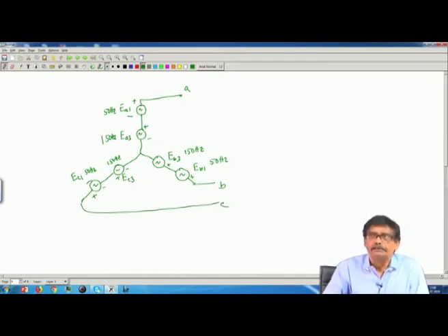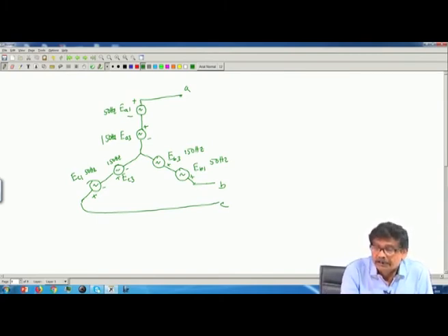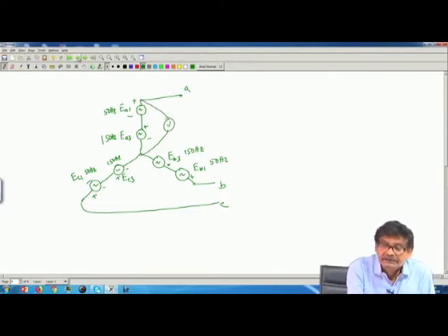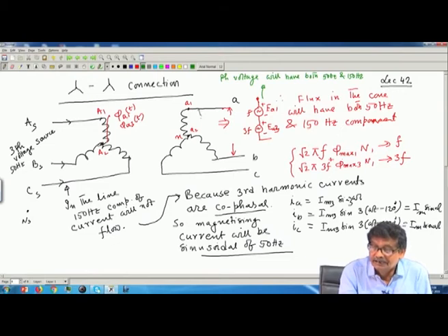Similarly, in the primary coils, do not worry about that. Now, if you take a voltmeter and connect it here, suppose I connect a voltmeter here, what is it going to read? There are two AC voltages of different frequencies, but this voltmeter reads RMS values. So the RMS value squared plus this RMS value squared, under a root, whatever the formula is, I will be able to calculate that RMS value.